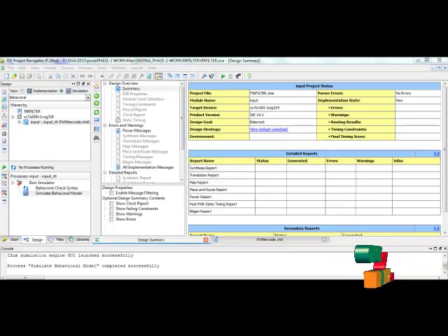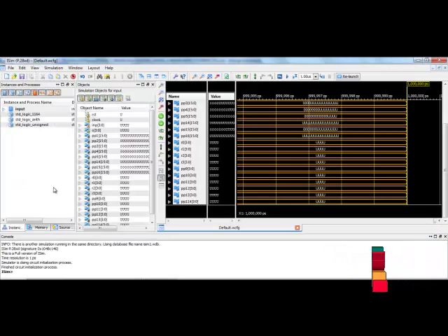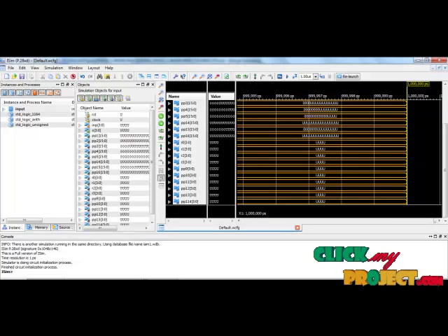Finally, we are going to see the output for our product. We are using Xilinx 14.2 version. For the project, we have to create a new project by clicking on File and New Project. Then a new source is added for the code. The VHDL option is selected and the storage area is also selected. For that we have to click on Project and New Source. Then we have to simulate the code by clicking on Simulate Behavioral Model. We are seeing the output for our code in ISim.